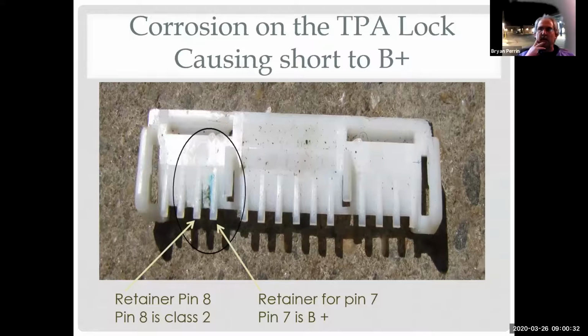Oh, absolutely. Yeah, all connectors, all circuits have a voltage spec and a parameter spec. If we're not in there due to corrosion, high resistance, induced voltage, induced ground, voltage drop due to a bad connection, the circuit's not going to work right.